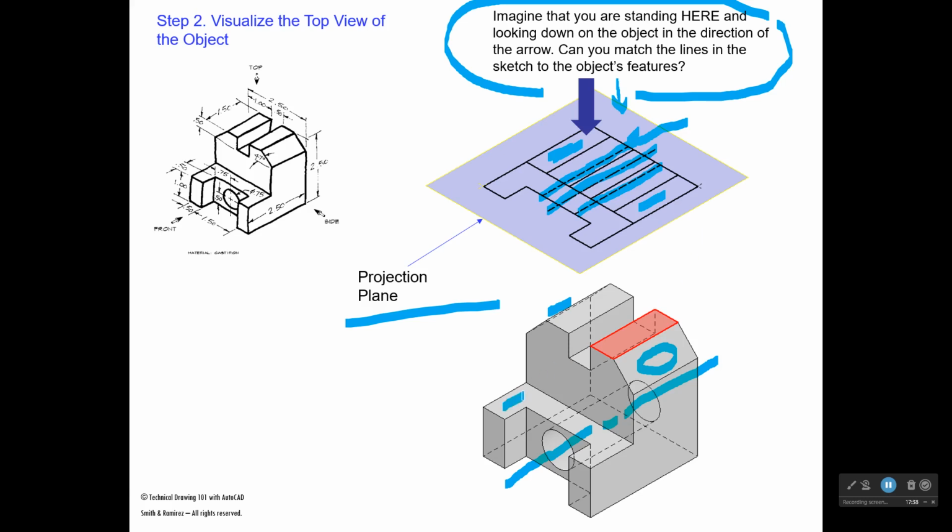I want you to notice that this plane right down here, this kind of horseshoe shape, projects up right up to here. Would you say you're normal to that plane? Well, you are, because when you look straight down, your line of sight is perpendicular to this entire plane. So that would mean that this plane right here, that horseshoe kind of shape, is probably true size and true shape.